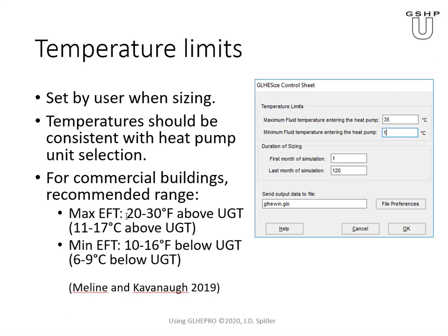And when I say undisturbed ground temperature here, I'm using this slightly differently. This would be the ground temperature that you've input for the ground surrounding the borehole. If you had urbanization and you measured the actual temperature and put it in, then you would use that, not what I was calling the undisturbed, meaning there was never any pavement or anything like that.